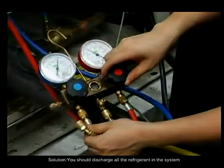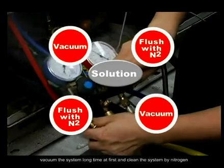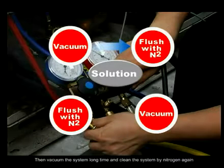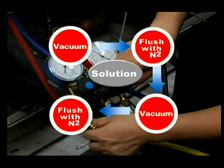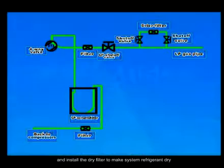Solution. You should discharge all the refrigerant in the system. Vacuum the system for a long time at first and clean the system with nitrogen. Then vacuum the system for a long time and clean the system with nitrogen again. Repeat the above process several times. You can change all the refrigerant oil if necessary and install the dry filter to make the system refrigerant dry.